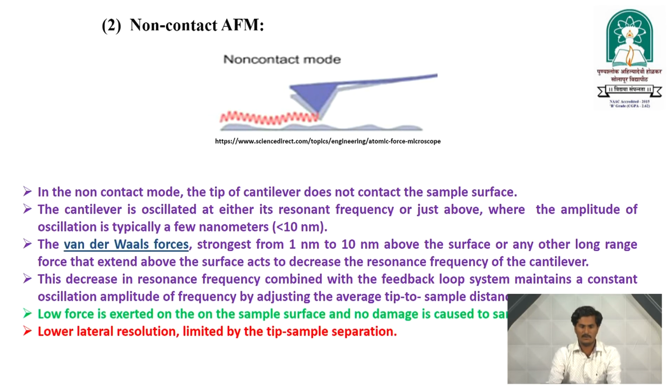In non-contact mode AFM, the tip of the cantilever does not contact the surface of the sample, and the cantilever is oscillated at either its resonant frequency or just above, where the amplitude of oscillation is typically a few nanometers, that is below 10 nanometers. The van der Waals forces, which are strongest from 1 nanometer to 10 nanometers above the surface, or any other long range forces that extend above the surface, act to